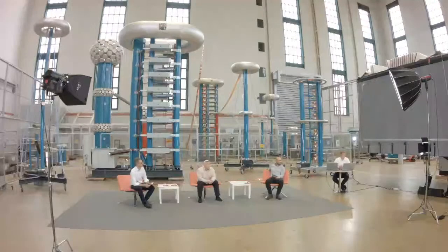Okay, next question. The PD pattern derived after noise separation is more important than the PD level as such, especially for on-site measurement, especially if the background noise is very high. Alex, I think that goes a little bit into your direction and experience. Can you agree to that? For me, it was a statement, not a question. I would say yes, it's absolutely right. The point is when you have to localize a PD source in oil-filled equipment, and you have more than one source.